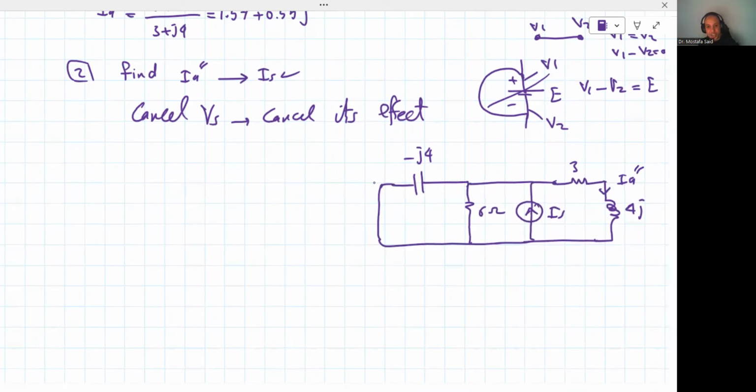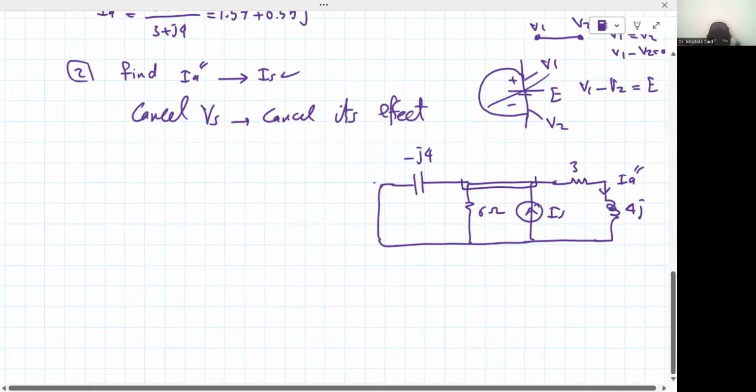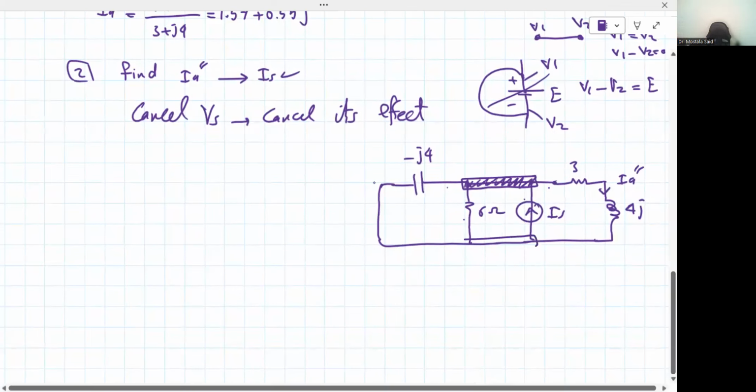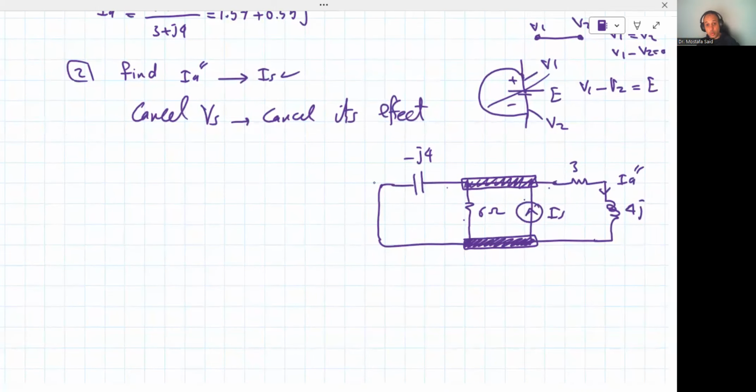So again, if we look here, the best way to solve it is using the nodal voltage method. So we search for the nodes with 3 branches or more. We have 2 of them. This one here is a node, with 4 branches actually: 1, 2, 3, and another node, which is that one here. 2 nodes with 3 branches or more. We ground one of them as you like. If you want to ground the top one and leave the bottom one, or vice versa, whatever you like.